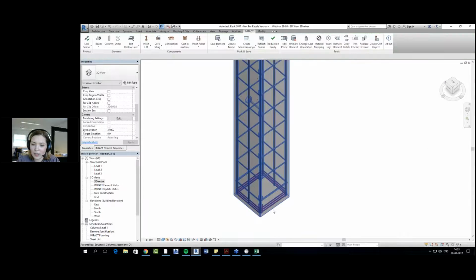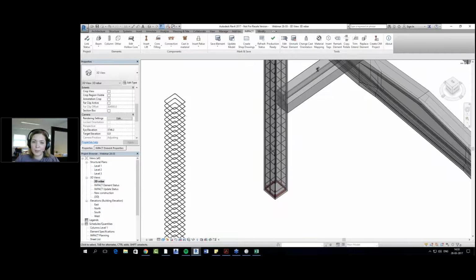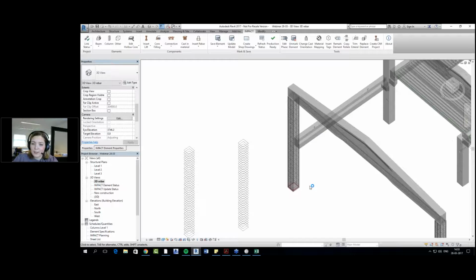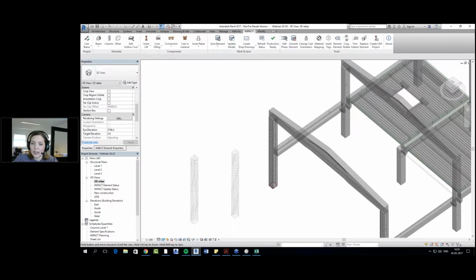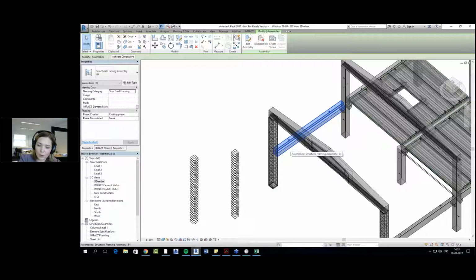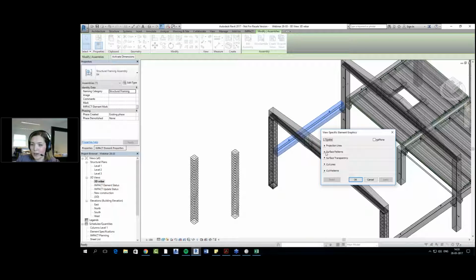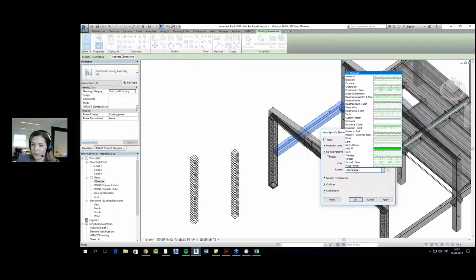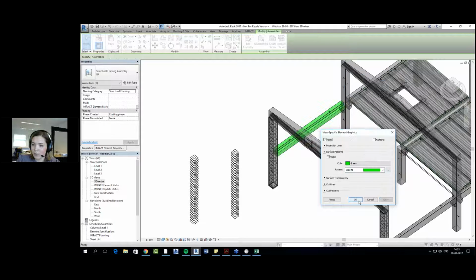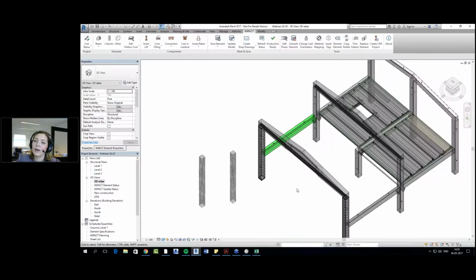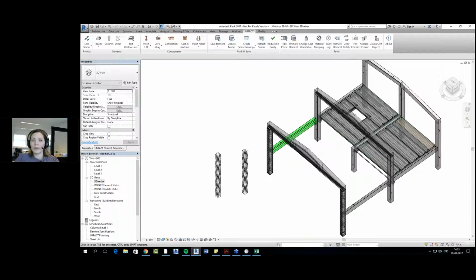So now you can see it gets a color, and it can be also added to the production sheets, so to mark out some of the parts. And this function is done very easily. You just take the element or any other object and you type in the shortcut EOD. And then you have this view graphics window where you say surface patterns. You choose any color you want. And then you click on solid fill. Apply, and it's OK.